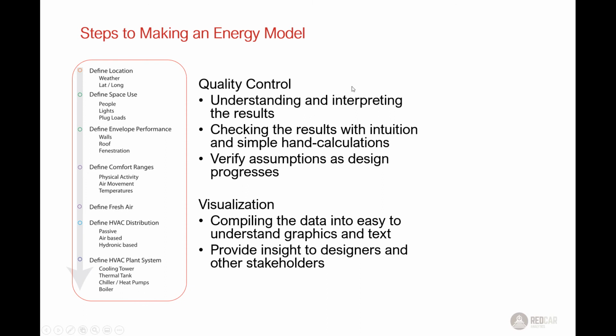Quality control is a challenge, right? There's going to be lots and lots of inputs, and we're also doing lots and lots of things by assuming that these templates are representative of our building. Are those plug loads in that template of that space type the most accurate for your client's office? Maybe not. And so thinking about how these inputs change the output is kind of the key to making a robust model. And at the same time, there's lots of ways you can do quality control.